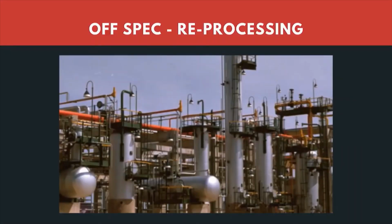The next way, if blending is not possible, is that we have to reprocess. For example, H2S presence in LPG is a test for the LPG product. If H2S is present, then even if you blend it with pure LPG, it is not going to get diluted. So, here the only way is to do the reprocessing.